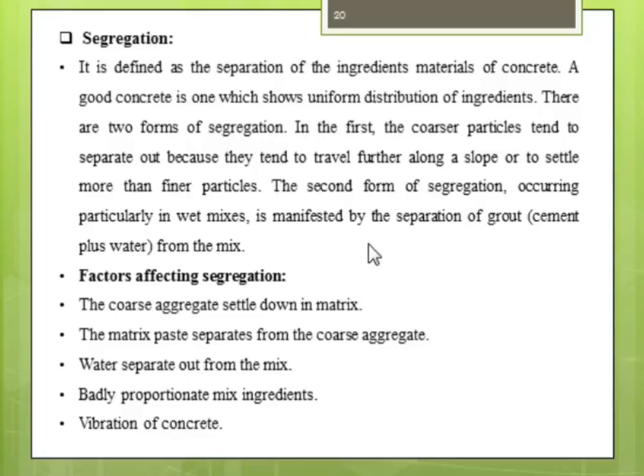When you remove the slump cone and the concrete collapses, the aggregate suddenly separates from the homogeneous mix. That is segregation, a separation of aggregates from each other, with no homogeneous mixture or bonding forming. Segregation and bleeding are not acceptable in any case of concrete.